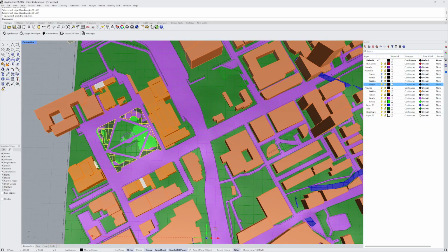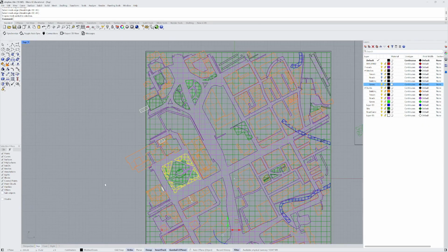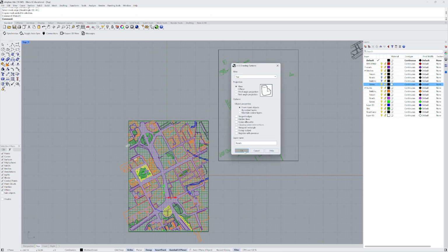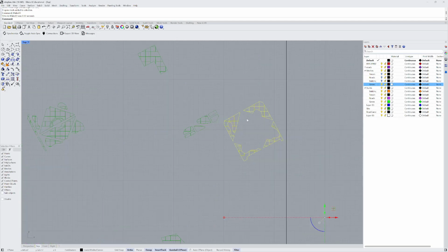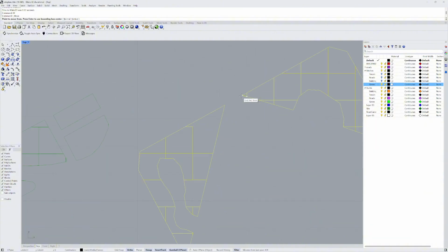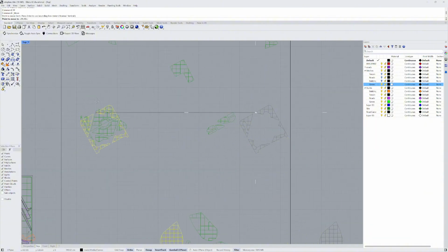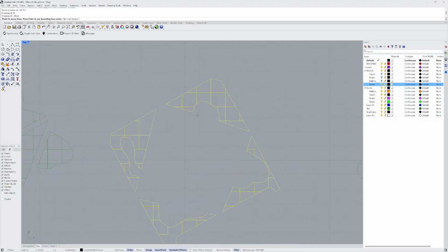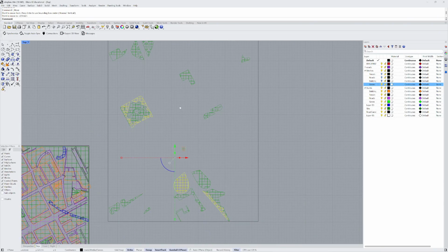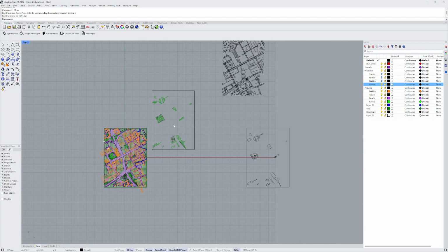So I could go back in the top view. I can do make 2D and select these. That'll also bring these ones out. And then I can bring this one, the corner there, to this corner here, and that should work. Perfect.